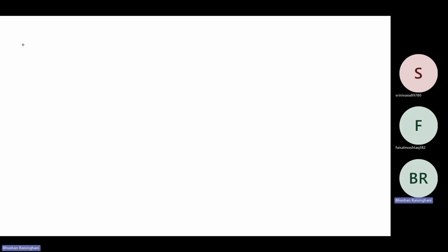Now, once you have CM and CR values, you will estimate, number one, your static eccentricity. So software also gives you these values and you have to estimate manually as well for each floor. So per floor, this exercise has to be done.